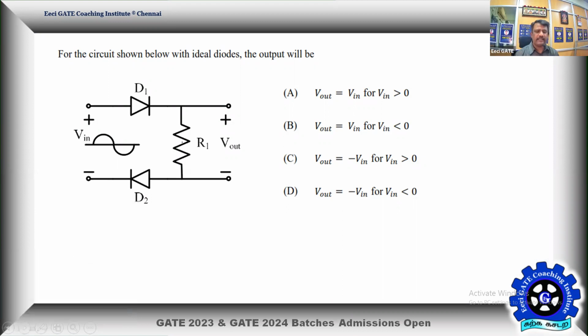Given diodes are ideal, that means an ideal diode in forward bias will act as a closed switch between the terminals anode and cathode. It doesn't have any potential, VD is equal to 0, but it can have any current ID. If it is in reverse bias, it is simply an open circuit. Reverse potential exists between anode and cathode, but the current through the terminals is equal to 0. Yes, that's the basic of an ideal diode.